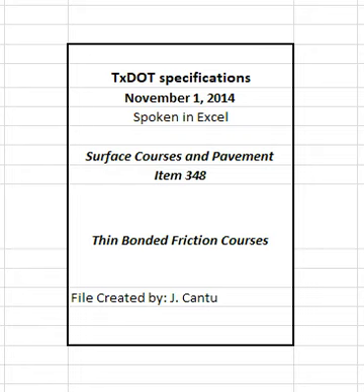4.7.1.2 When not using a thermal imaging system, place mixture when the roadway surface temperature is at or above 70 degrees Fahrenheit unless otherwise approved or as shown on the plans. Measure the roadway surface temperature with a handheld thermal camera or infrared thermometer.